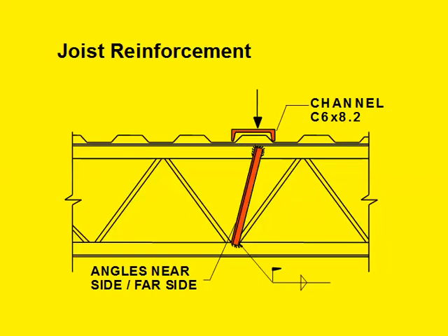It happens so frequently. I might add that there's some very, very nice new provisions in the AISC 2005 specification on the design of single angles. We used to have some really complicated stuff there, but the 2005 spec has a procedure that allows you to use an equivalent slenderness ratio and go right to the column tables, and it's very nice. So look for that in the 2005 spec. You might consider adding a beam.